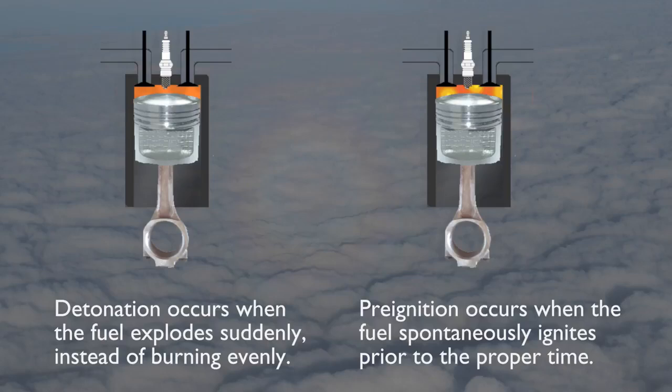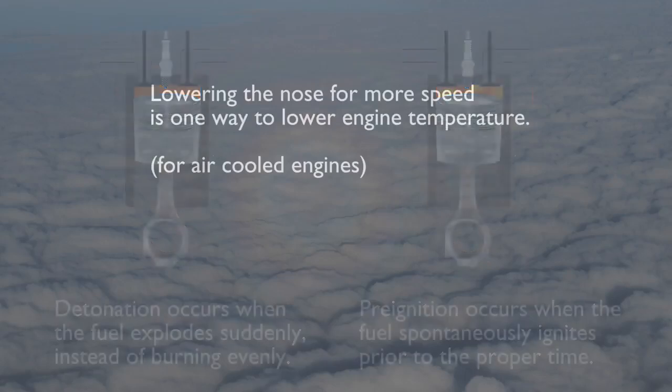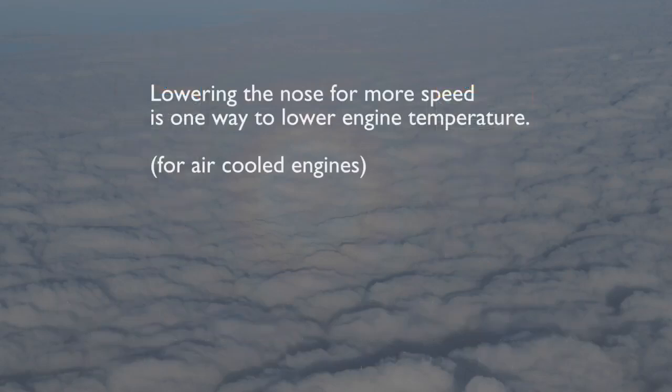To prevent detonation, the pilot should keep the temperature of the engine within the recommended limitations. Lowering the nose will allow the airplane to gain speed, which will eventually lower the engine temperature.